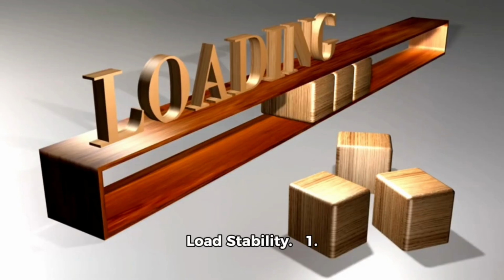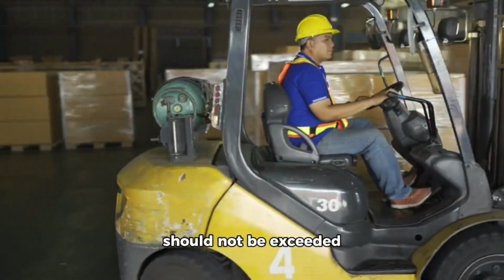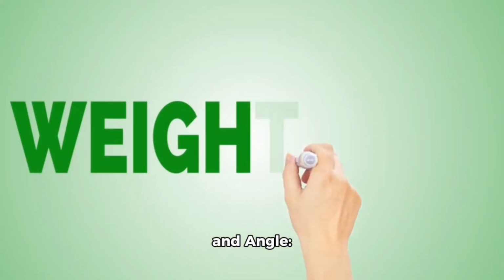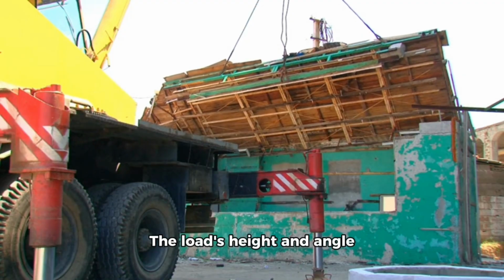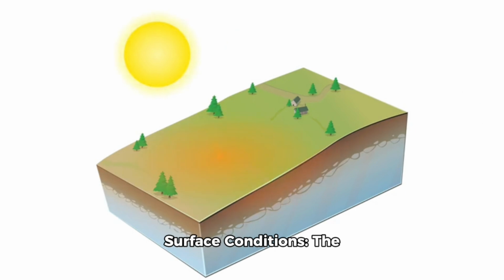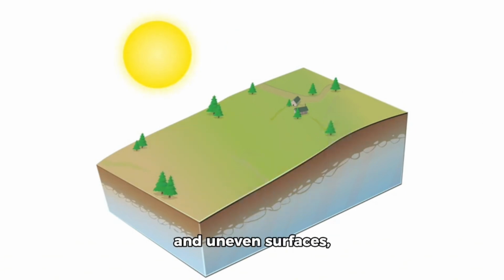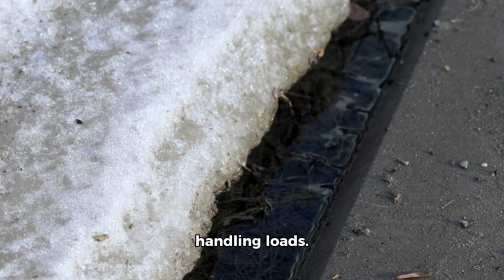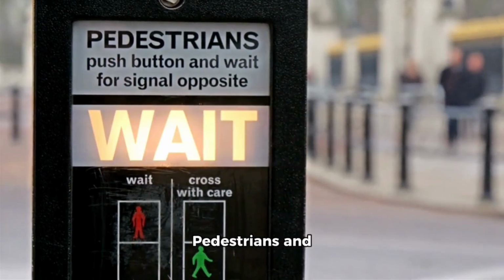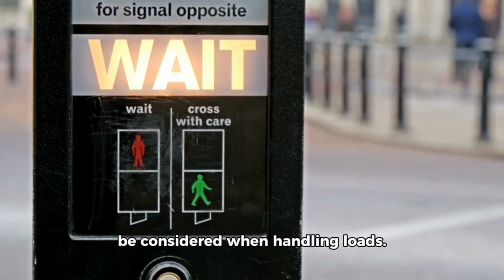Factors affecting load stability. 1. Forklift capacity. The forklift's capacity should not be exceeded when handling loads. 2. Load height and angle. The load's height and angle should be considered to prevent tipping or falling. 3. Surface conditions. The surface conditions, such as inclines, declines, and uneven surfaces, should be considered when handling loads. 4. Pedestrian and obstacle awareness. Pedestrians and obstacles in the surrounding area should be considered when handling loads.